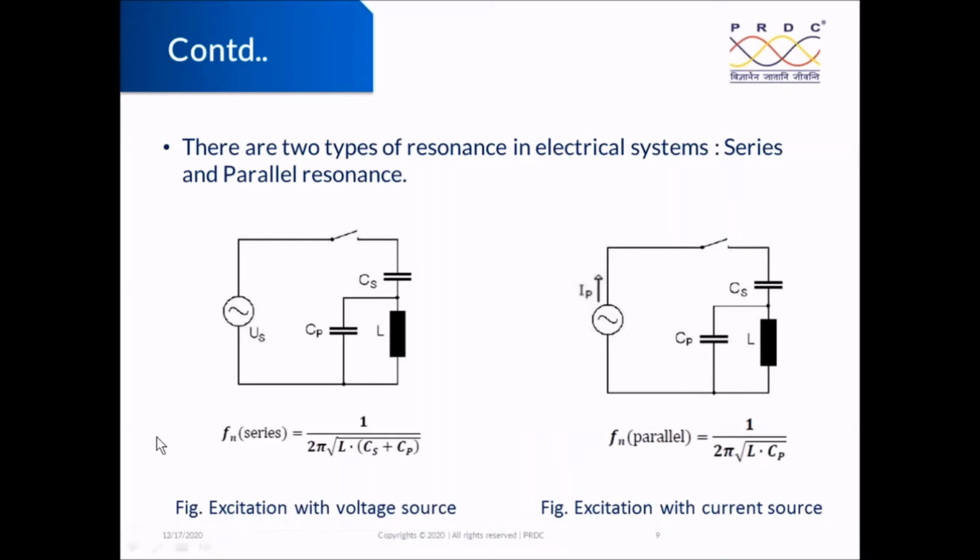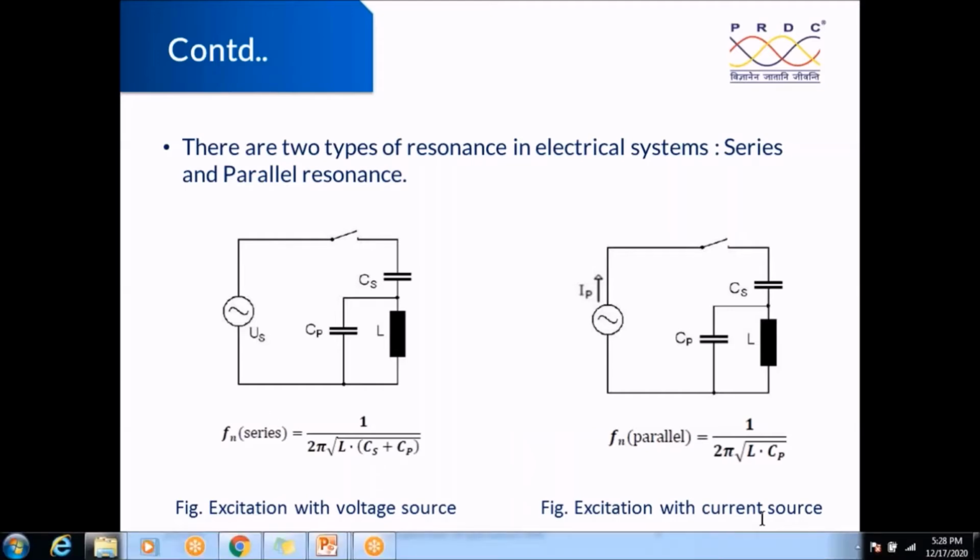Now, once we have the shunt compensation and a long line, there is a possibility of uneven phase operation, meaning, for example, a stuck breaker operation, or maybe one pole is open and the other two are closed. That can come from two things. One is intentional, that is, we normally use single phase tripping schemes. In case of EHV transmission lines, we use the single pole auto reclosing phenomenon, right? That is what the single phase tripping scheme is.